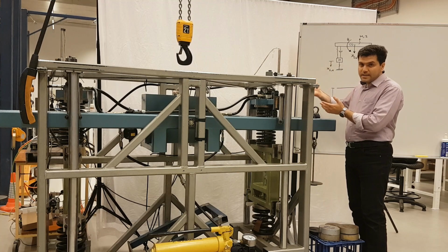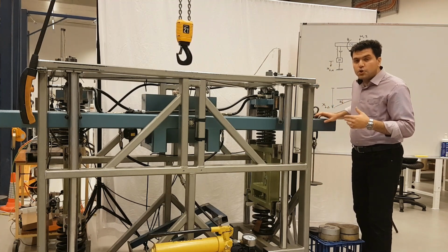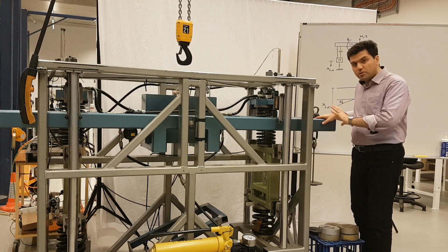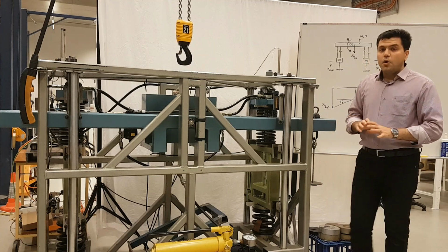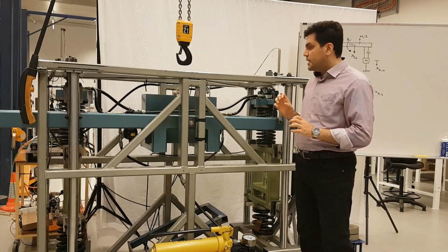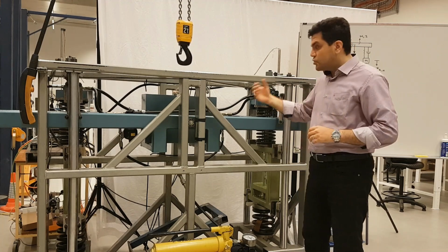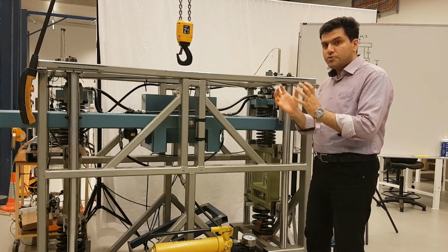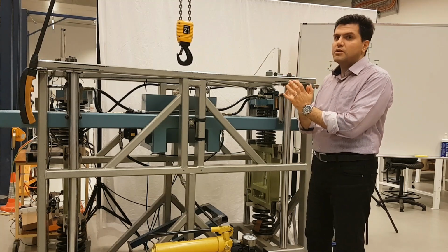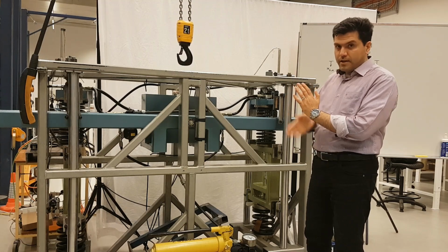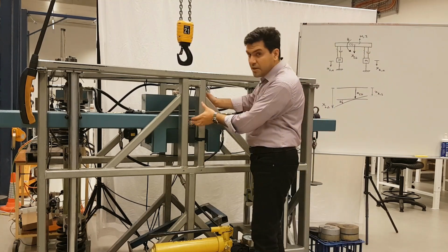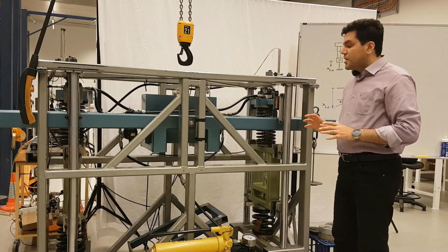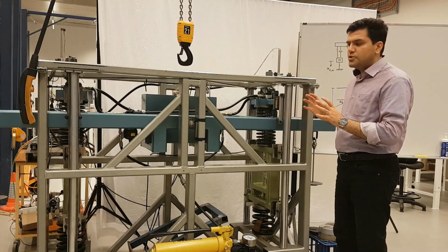And then we release it, and then we can excite roll mode. But the point is that by this action, we excite both roll mode and bounce mode, because if you want to excite only roll mode, you need to keep the center of gravity. You need to actually make some constraint to prevent the center of gravity from vibrating in the vertical direction. Meaning that you need to basically keep the center of gravity here by some constraints, which we don't have here, such clips or such constraints.